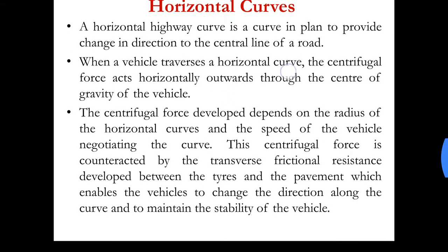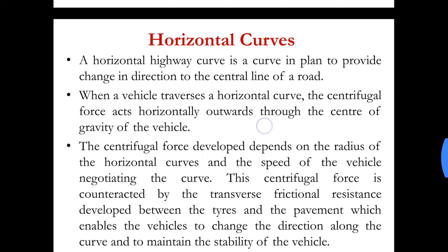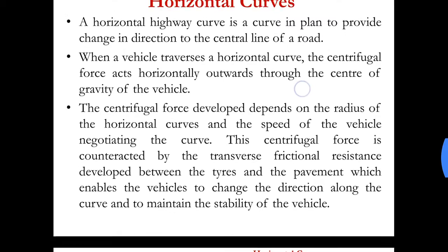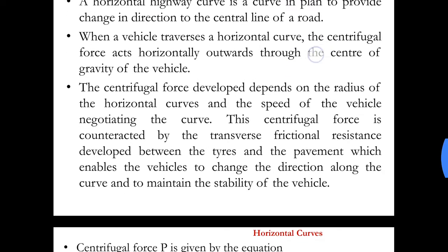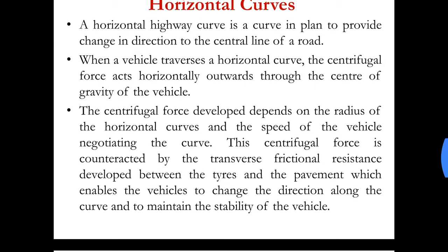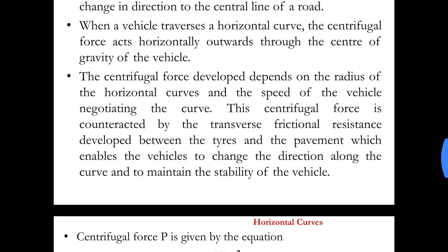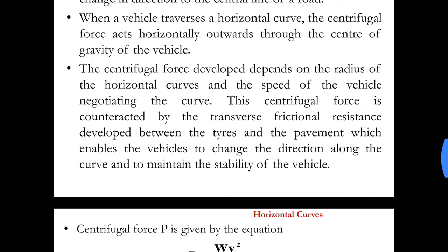This phenomenon of centrifugal force we have already studied in our lower classes, during our 12th in physics, that whenever a body or a vehicle traverses a horizontal curve, it is subjected to an outward force which is known as centrifugal force. It is required that we counteract this outward force so as to provide safety and stability to our vehicle. The centrifugal force developed depends on the radius of the horizontal curve.